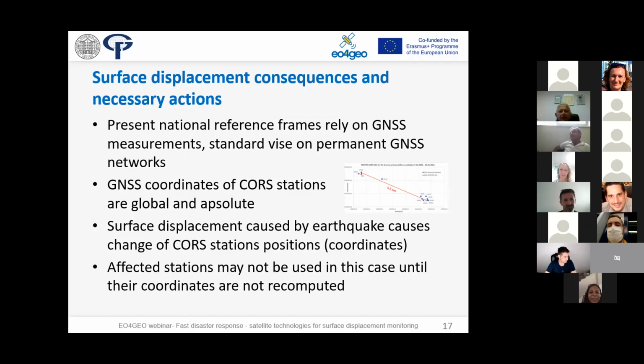So it is not like in the, under quote marks, old times when we had our local reference systems, which were more or less moving with the surface because they were defined based on fixed points on the Earth's surface. This is today not the case. We have a system in space which is not affected by the surface movements of the Earth.